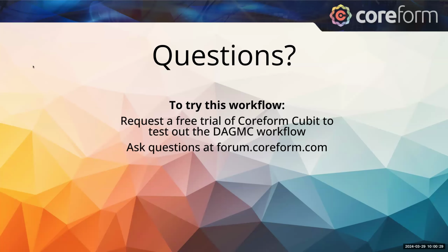Okay. So there's additional questions then, I guess here's one last one from Ibrahim. Are we able to use a second order hex mesh in volumetric meshing for DAGMC? Yeah, we are not yet. Second order elements can be really tricky. They add a level of complexity to the particle transport, in particular the ray tracing. Certainly not impossible. It's just not something that we've explored currently with DAGMC, but it's definitely of interest. And we actually have a couple research proposals out to try to enable that within DAGMC and OpenMC.